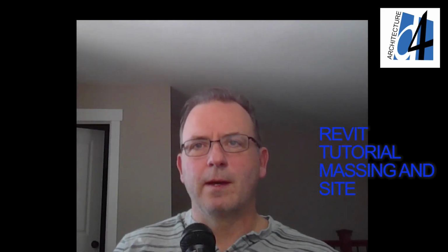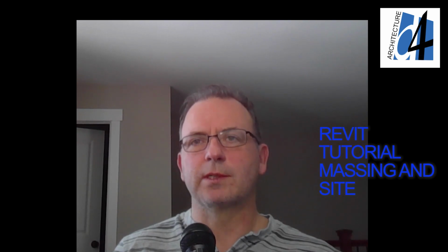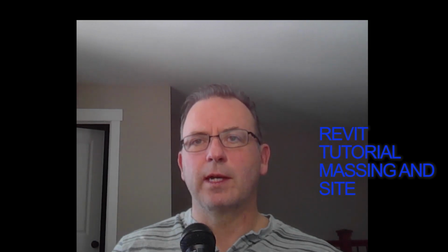Hello and welcome. My name's Derek, and today we're going to be learning how to do a conceptual site plan and model inside Revit using the massing and site tools. And we're also going to extract out XYZ coordinates out of Google Earth to use as our base to create our massing model. And then we're going to add walls, roofs, windows to the massing and see how they work together.